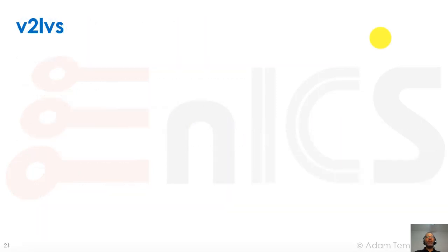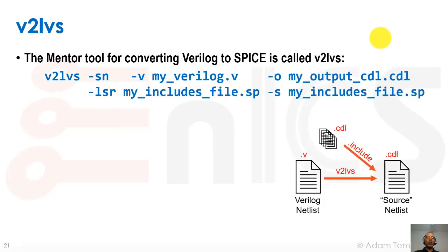Okay, so now that we've collected all of our CDLs, our SPICE netlists, we can run V2LVS, which I mentioned many times in the last two parts of the lecture. V2LVS is a Mentor tool. V is for Verilog, 2 is to translate to, and LVS is what we're doing now. Other vendors have their own tools. I'm just going to show you with the Mentor tool that comes with Calibre. So we run V2LVS with all these different types of options.